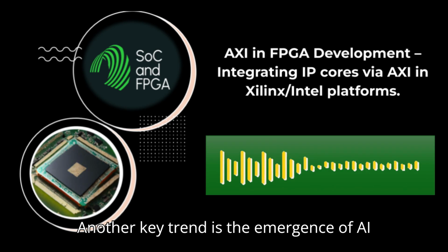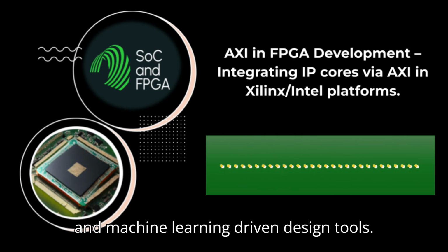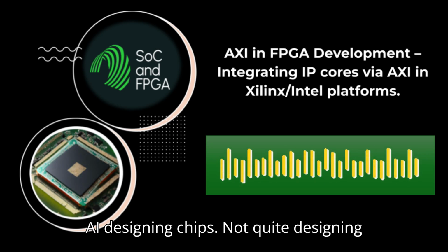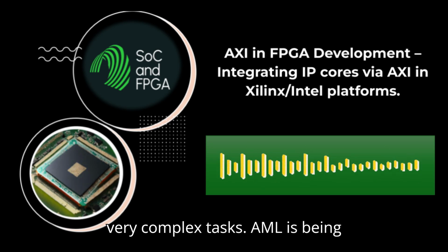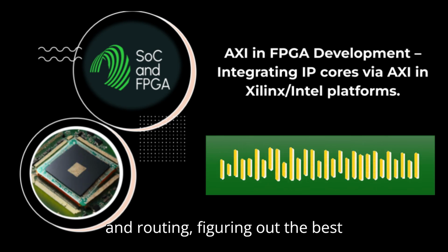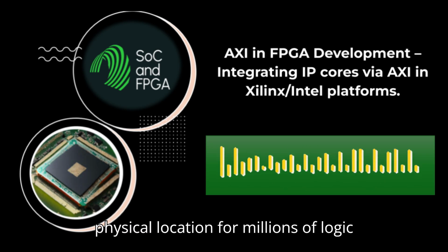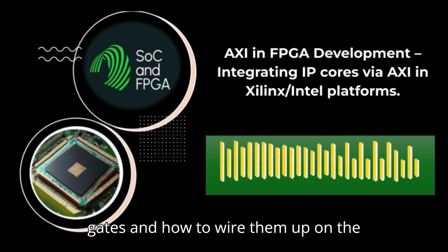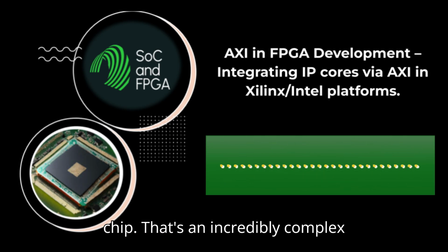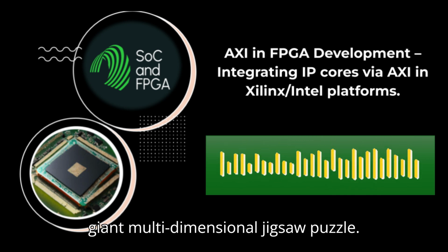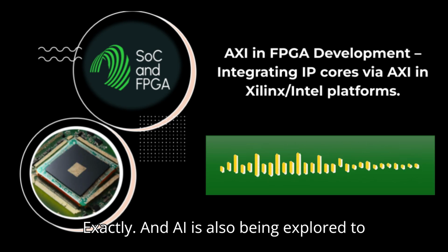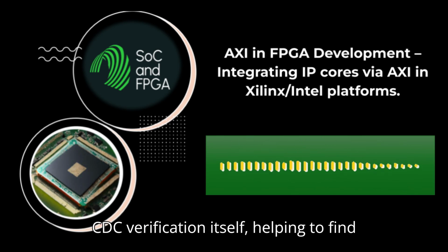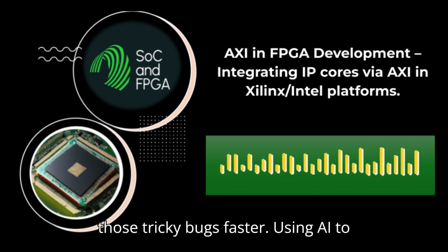Potentially, yes. Another key trend is the emergence of AI and machine learning-driven design tools. AI designing chips. Not quite designing them from scratch yet, but assisting in very complex tasks. AI/ML is being used to optimize things like placement and routing, figuring out the best physical location for millions of logic gates and how to wire them up on the chip. That's an incredibly complex optimization problem. Like solving a giant multidimensional jigsaw puzzle. Exactly. And AI is also being explored to enhance the accuracy and efficiency of CDC verification itself, helping to find those tricky bugs faster.